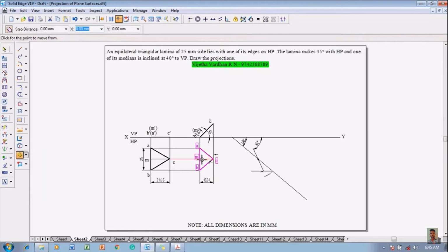Now one has to select this front view properly, then go to a move command, move with respect to point M using the midpoint, and then M has to be positioned exactly on the M position, and then go for rotate command. Rotate in such a way that M is fixed and C should be obtained on the new point wherever we have marked it. Now the rotation has been completed.